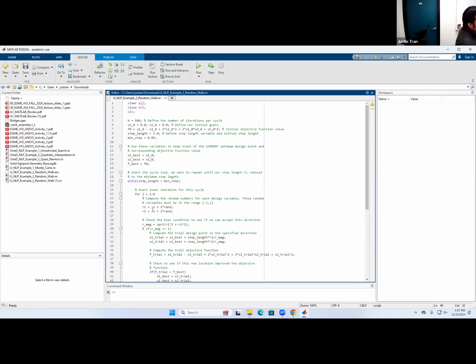Is the X1 and X2, is that usually defined as like the measurement of a distance? So if you're doing an airplane wing. Yep, that's whatever your design variables in your problem are. So for our problems, that's most of what you're going to be designing for, the optimal dimensions. And so those would be lengths of some kind. But you can also design things where maybe you're choosing a material. So maybe you're optimizing over the Young's modulus and the density, things like that too.